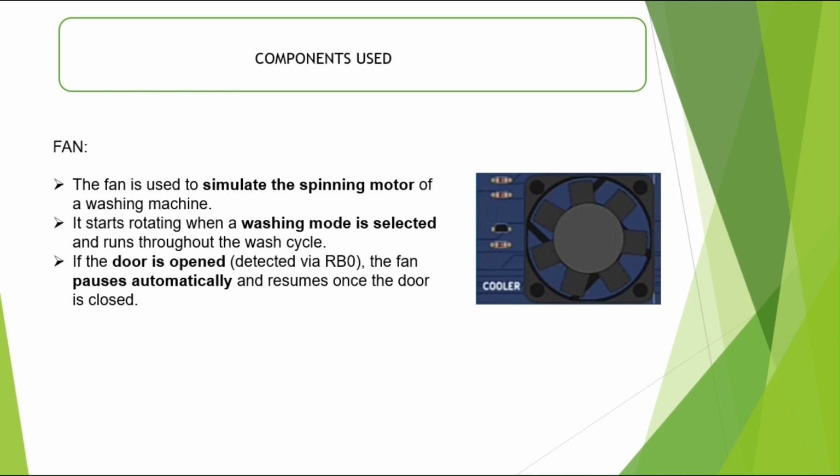If the door is opened while the fan is spinning, which is detected by our RB0, which we discussed earlier, the fan will pause automatically. This is a crucial safety measure preventing any virtual accidents. Once the door is safely closed again, the fan will automatically resume its operation and continue the wash cycle.